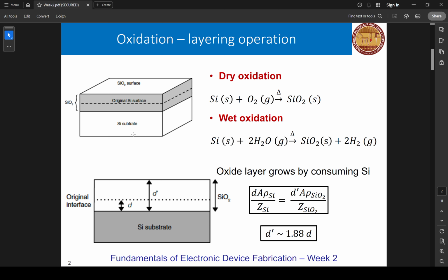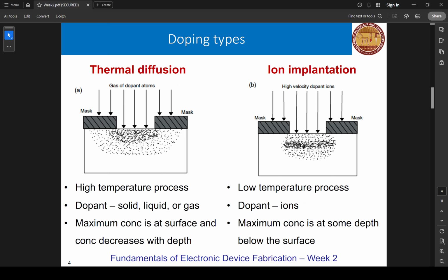I can't imagine how that happens. In the presence of an oxide layer on the surface of the silicon wafer during the drive-in of the dopants, it can lead to an increase in N-type dopant just below the interface, as he has said in the video. But what it actually is, I didn't understand.